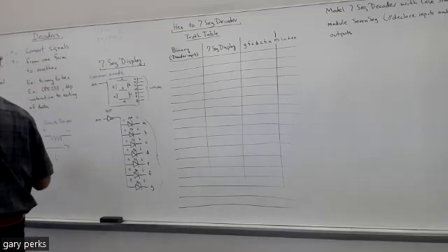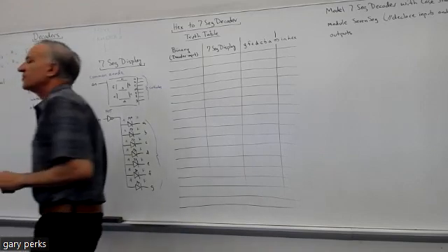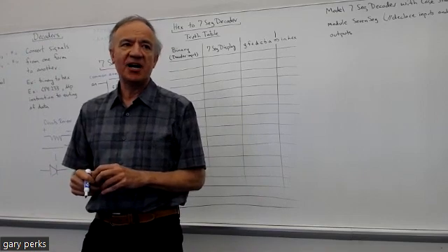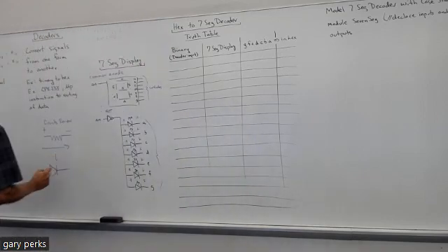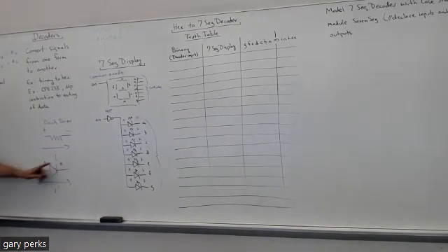Okay. Well, diodes and LEDs, like resistors, can only absorb power. They can't supply power. And current through an LED will only flow anode to cathode. So to get current to flow through a diode, the anode has to be at a higher voltage than the cathode.